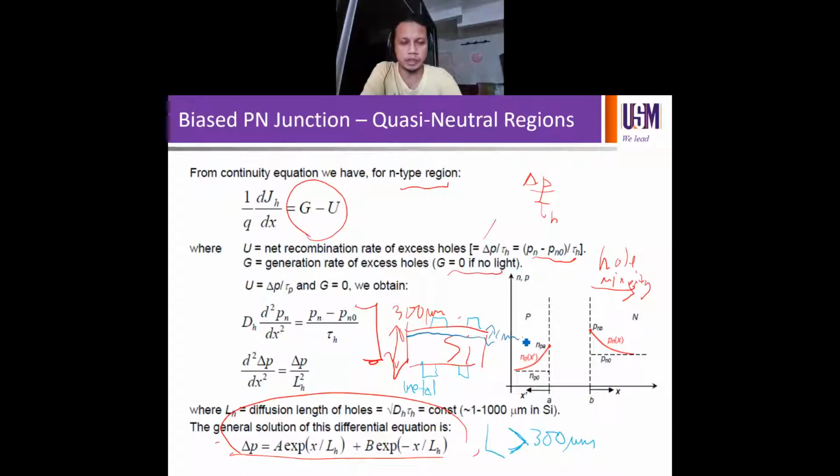So say the front is N type and the back is P type; try to relate to this curve on the right. Say your electrons from the N side diffuse into the P side and cross the junction. The junction is only about 1 micron from the surface, right? So how far do they still have to travel through the silicon to get to the rear metal contact?